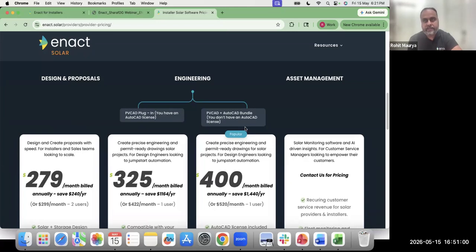We also get a detailed 8760 file, which is an output file that comes out from the pre-sales tool, which gives you an hourly projection of the flow of energy, be it the grid consumption, the generation, how much charge the battery is going to have, and how much the battery is going to discharge. But yeah, we do also have the calculations for LCOS so that we can bake into your final proposal documents.